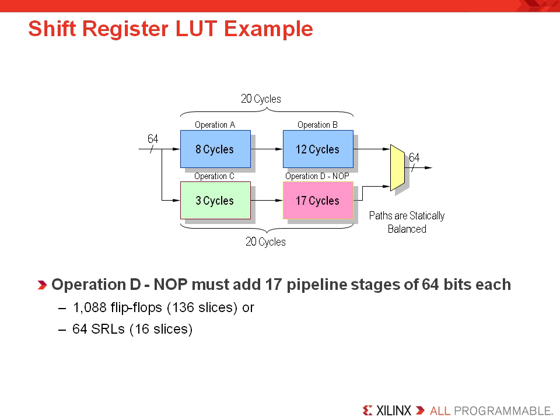Because there are so many registers in FPGAs, pipelining is an effective way of designing to increase design performance. Because pipelines can sometimes become unbalanced when too much logic must be generated, it is necessary to delay some of the signals. And this is one of the best uses of the shift register LUT functionality, that is, to add balance to pipelined applications.